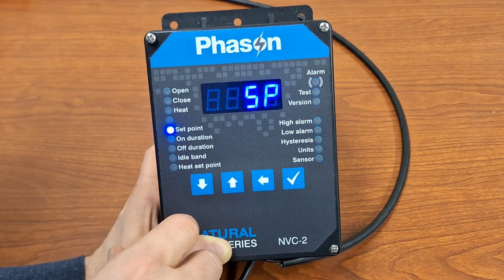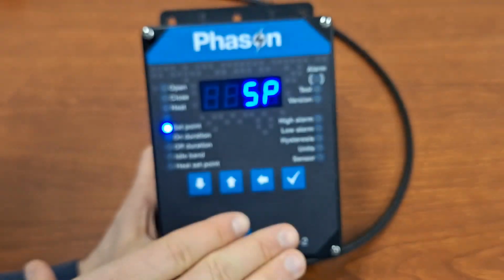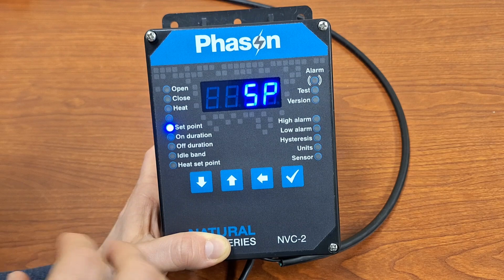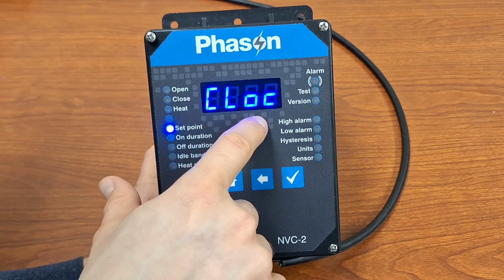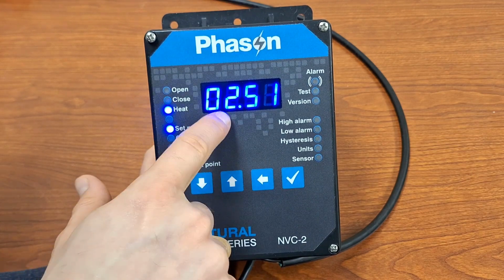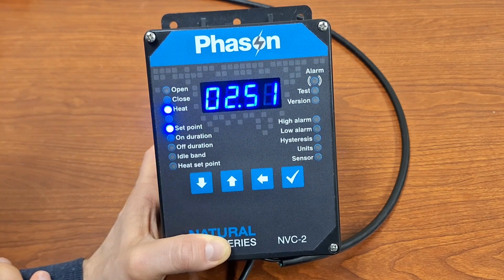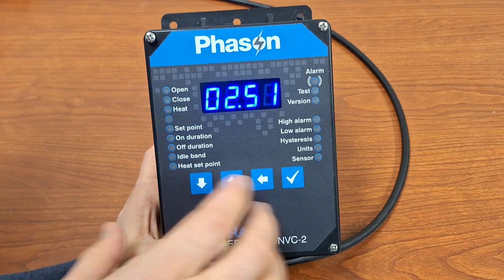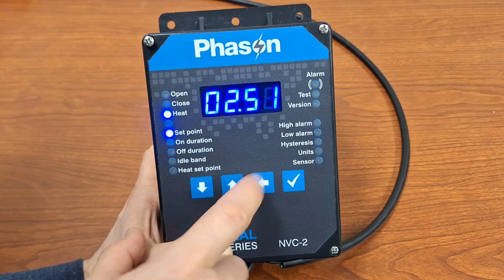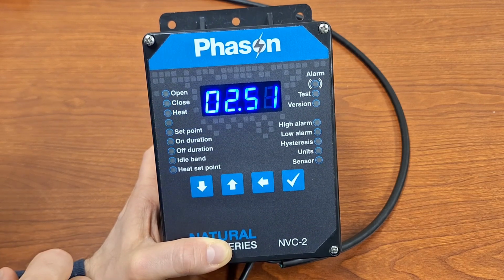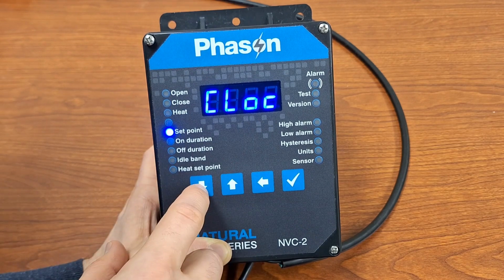If we do not want to use a set point, but rather we want to have a set point that is moving and adjusting itself, and we want to automate that, we can use the growth curve. So first off, actually, we would want to set our clock. So if we go in here, we can see 2:51 is the current time. You'll want to adjust that so that it is what your actual current time is. If I were to hit enter, you can see I can adjust that time. Then I will go back and back. All right, so there's our clock setting.